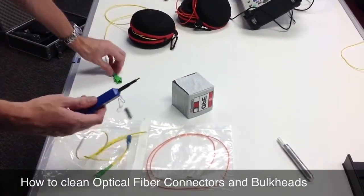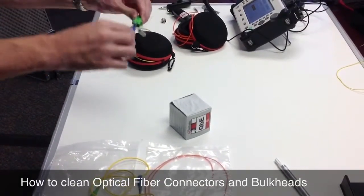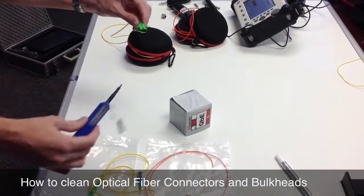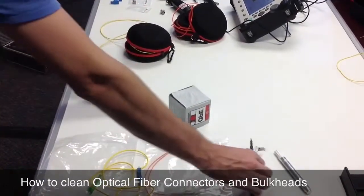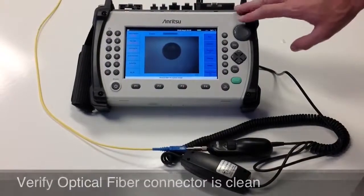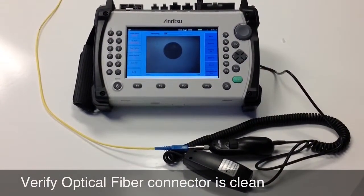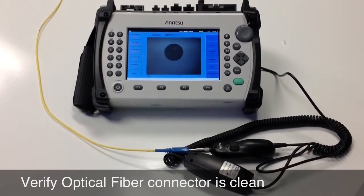If the dirty connector is contained within a patch panel, you can use a bulkhead cleaner in order to clean. Once the connector has been cleaned, rerun the VIP analysis in order to determine whether it is now passing.